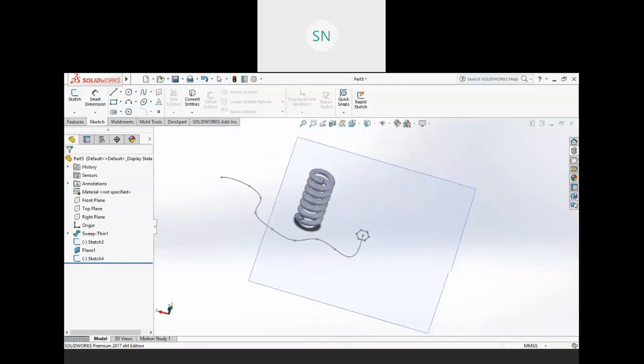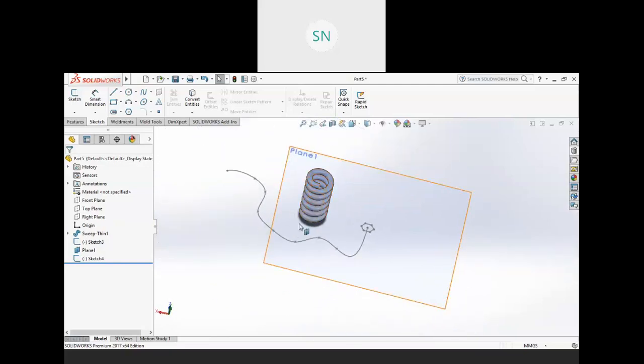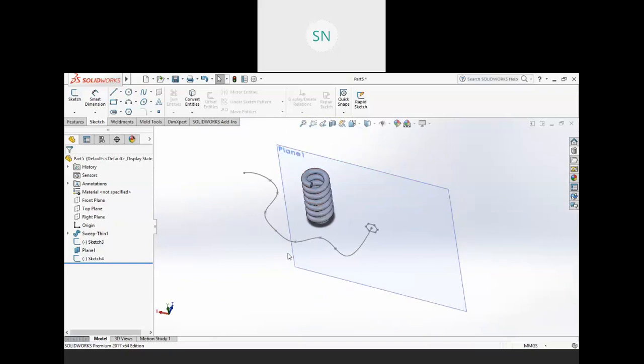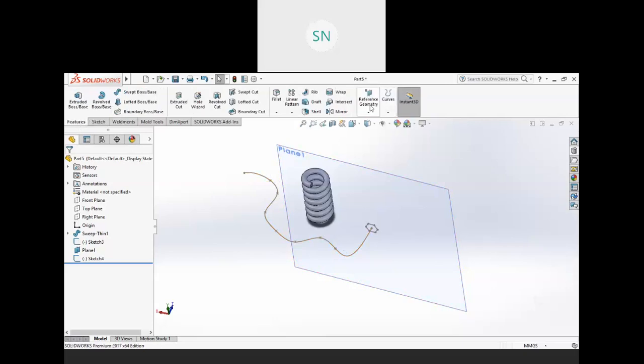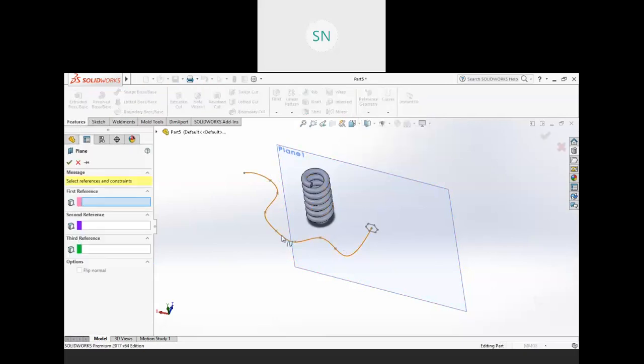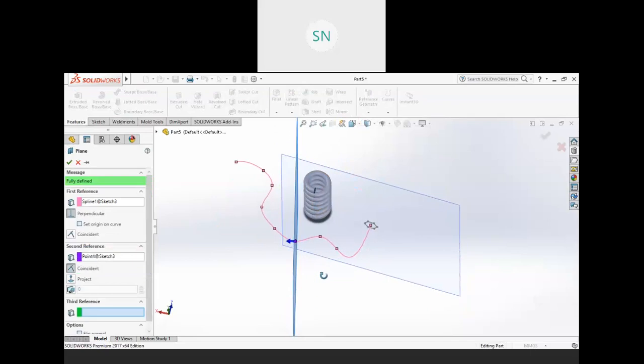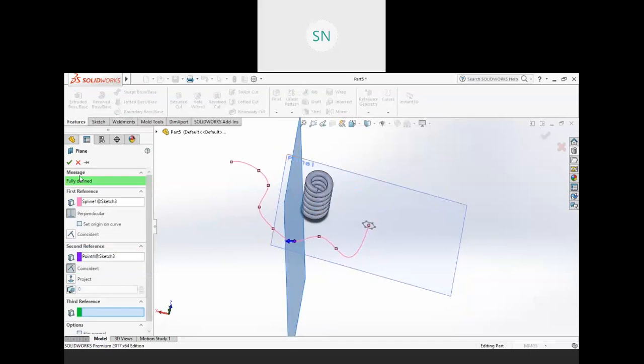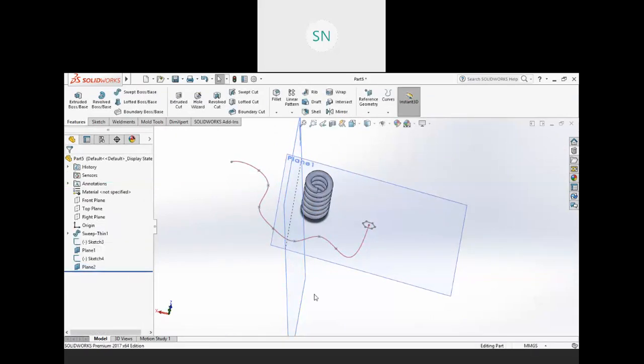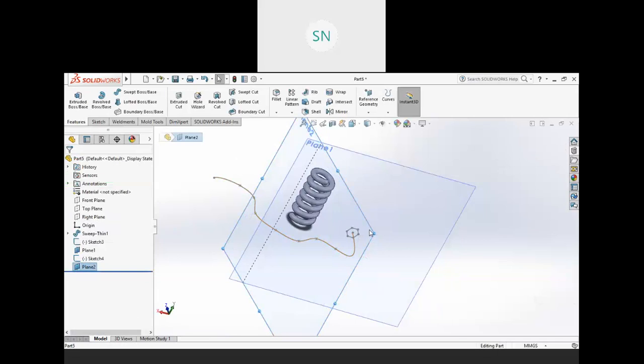Now for example, you want to add some more cross sections over here, like instead of sweep, now you change your mind and I want to create a lofted geometry over here along this path, right? So create more planes like this plane on this curve at this point. So again, this is also a perpendicular plane. Okay, and you can sketch a new profile over there.